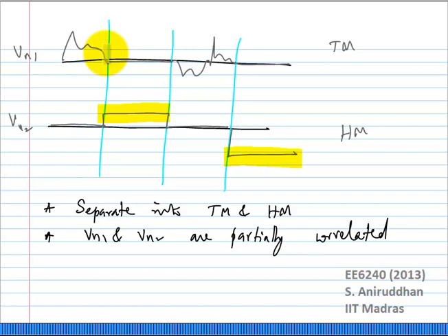So really the noise you have to worry about is the very, very low frequency noise, which doesn't discharge very fast. The components for which the RC bandwidth is significant are the noise sources for which you need to think about correlation. Okay, so which is the point I was coming to.